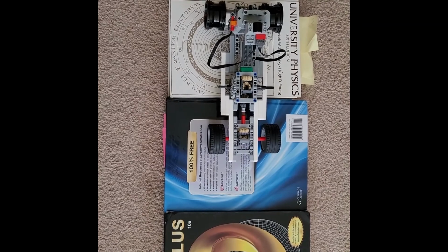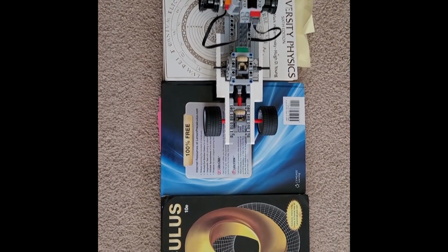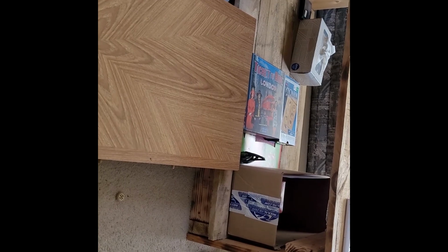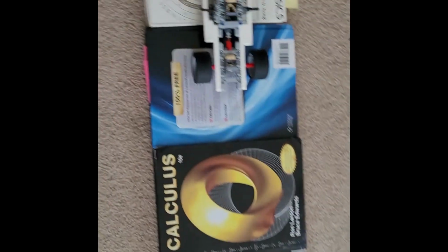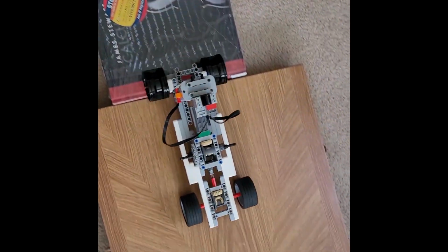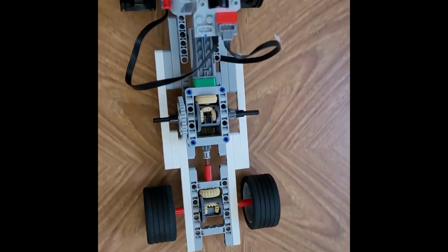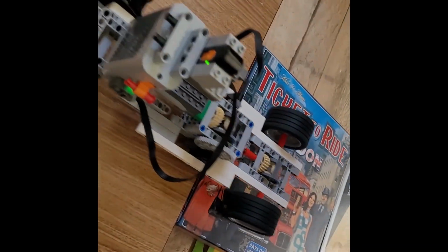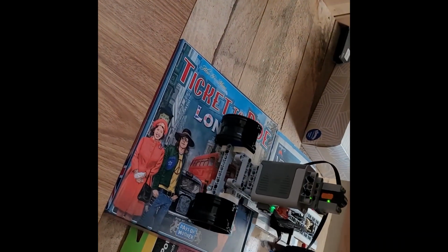So I have the car here set up on its test track, which goes from this flat terrain here, which is the textbooks, to the table sectioning, which is an incline, up underneath the coffee table onto the board games, which is going to be our flat terrain again. So let's get her moving. Currently she takes off in first, goes into second. Now as we climb up this hill, you can see that we are locked into first gear, and as we come up to this plane up here, we're back down to second.